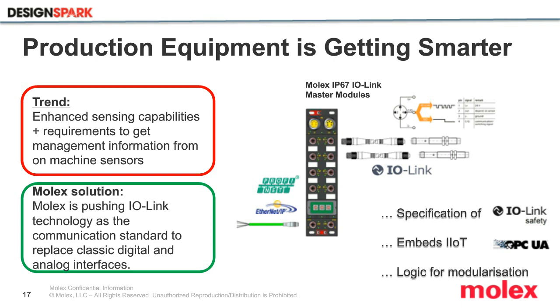The target here is to connect all kinds of sensors which are in a dedicated functional unit of the machine, to connect all sensors which are digital, analog, or with native IO-Link communication support, and to interface them with the traditional Ethernet-based network of the different PLC manufacturers, like Profinet or EtherNet/IP. We see here in this module the central point of the infrastructure of tomorrow, and